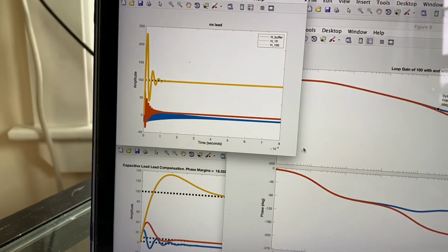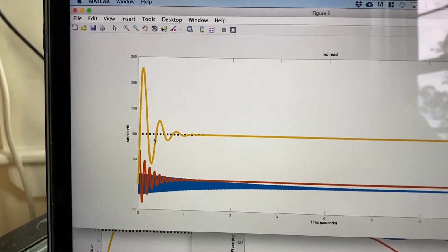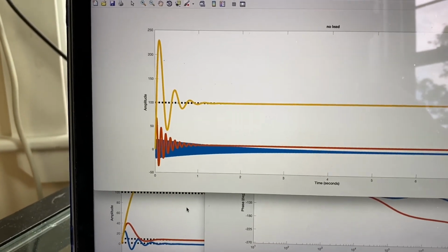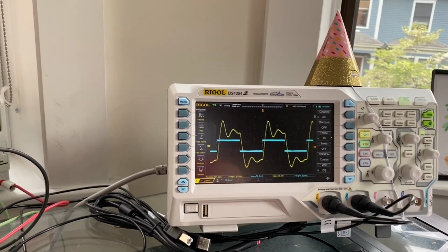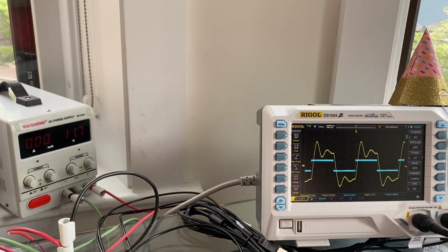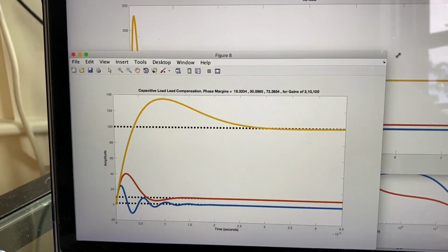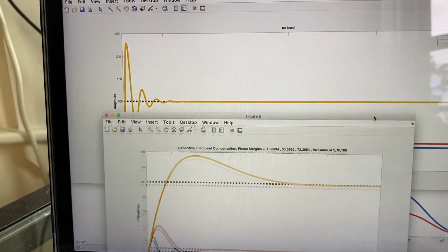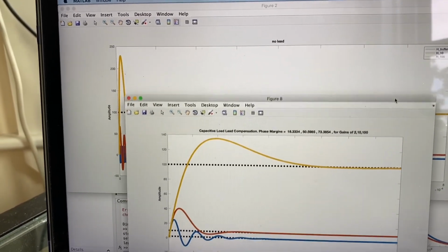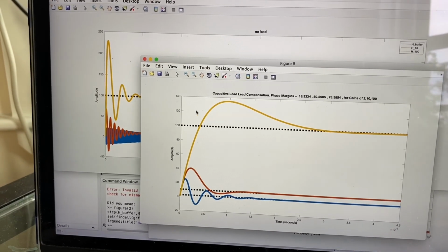And just to look in the time domain, we can confirm what we're seeing. Here, obviously the higher curve is the higher gain. This is uncompensated versus compensated. Still a little bit of overshoot, and we see there's a trade-off between you're removing oscillations, but now your rise time is slower and stuff like that. But your overshoot's much better, much lower, and your damping's higher.